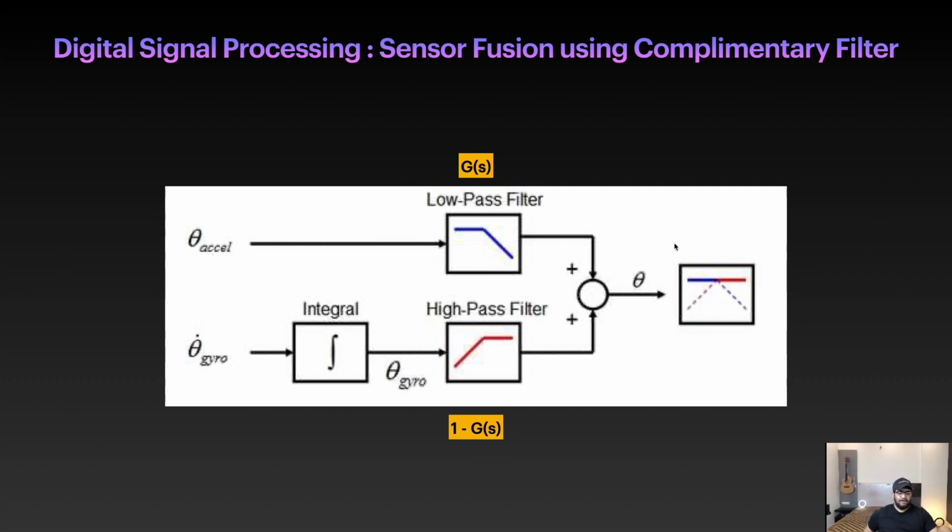And you can see my excitement, because when you actually implement this, it's a very powerful concept and very easy. Even for microcontrollers like the Arduino, you can implement complementary filters with some libraries. There are some open source libraries that help you implement a complementary filter, and if you are into that, I would highly recommend you do that and see for yourself. So again, this is called sensor fusion, and at the end you get a useful value: an estimated degree of one particular axis, which you can definitely use to your advantage. So that was called sensor fusion.